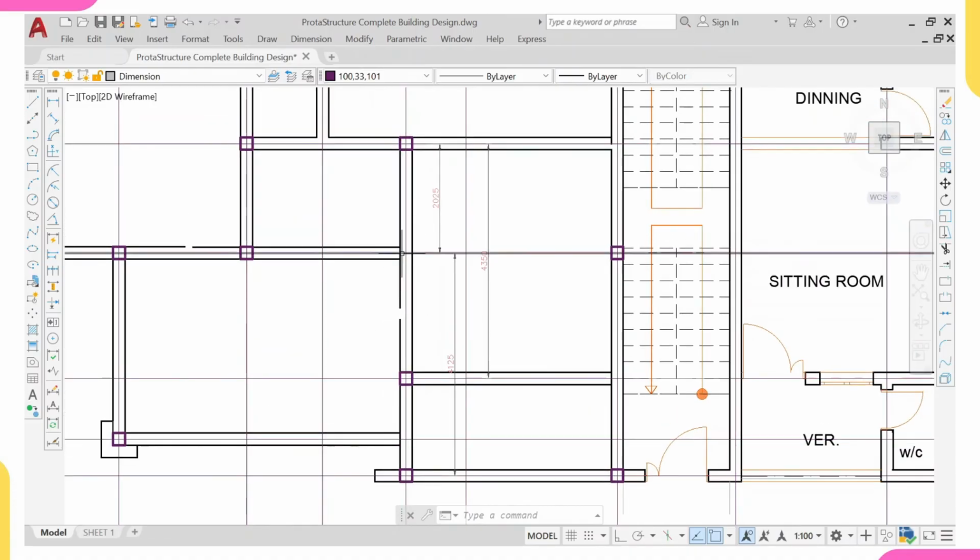But if I bring that column to this point, even though this is a slab and this is a slab, at least the point load has reduced, and the load coming from this slab is no longer that much because this is a beam. So the load is just from this small slab, and also from this portion, this rectangular portion, that will be coming to this.